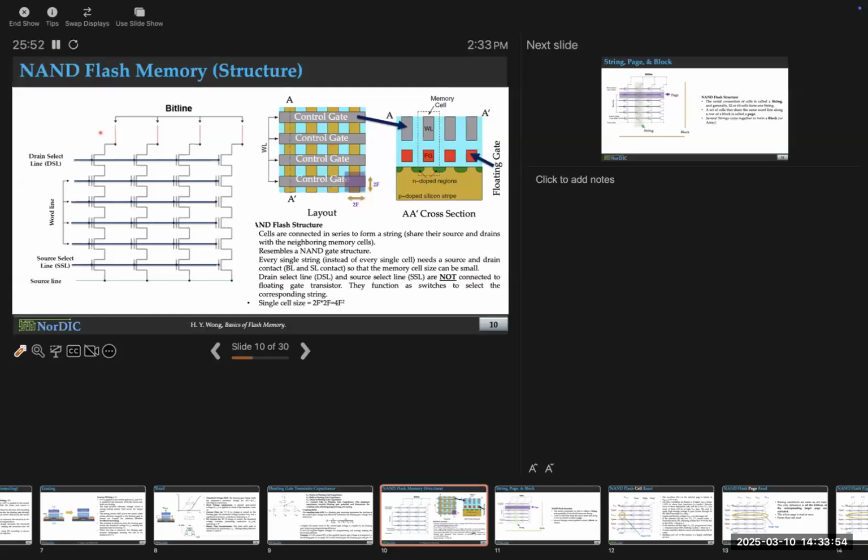Have you designed one? In a 2-input NAND gate, NMOSes are in series. 3-input NAND gate, NMOSes are in series. If you have 4-input NAND gate, they are always in series. NMOSes, and we are dealing with NMOSes here only, not PMOS. Okay, if there is a choice between N and P, always go with N. Easier to handle. Electrons are easier to deal with.